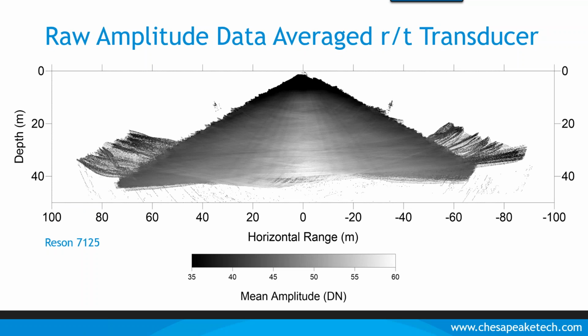So in this case, the artifacts are held steady relative to the transducer, but all the transient noise from the real seafloor actually gets averaged out. And what you're left with is an extremely accurate directivity index and beam pattern of the sonar system itself. This is the average amplitude for any depth and range from that sonar system.